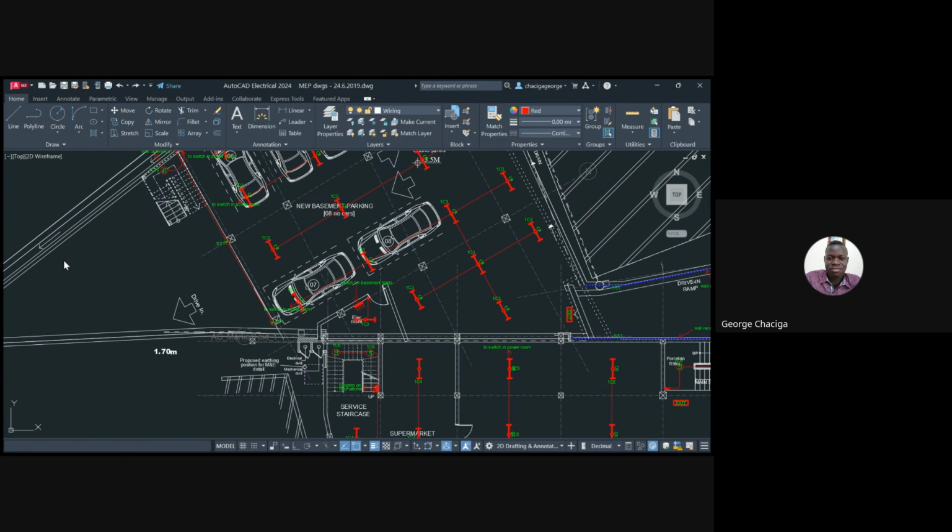So this 0.5, remember, there are characteristics of bulbs, which is called inrush current. I told you to design, you must have the background of engineering in you. If you're not familiar with inrush currents in electrical equipment, please go do some reading about that. Any design engineer or even design draftsman, you must drill into research, be ready to face research. There is a characteristic of inrush currents in bulbs. That inrush current can go up to 10 times the initial current.